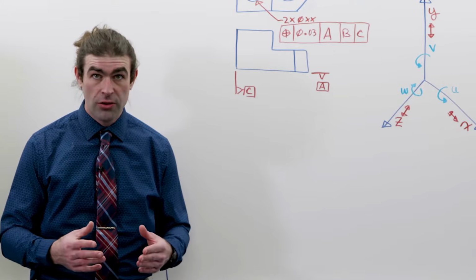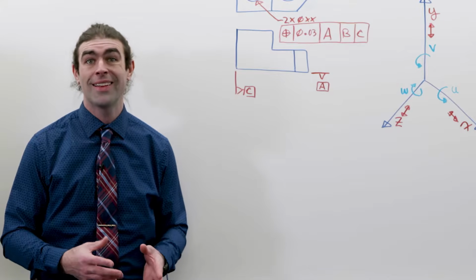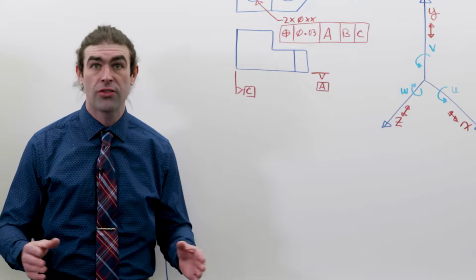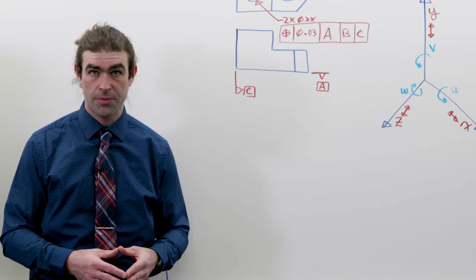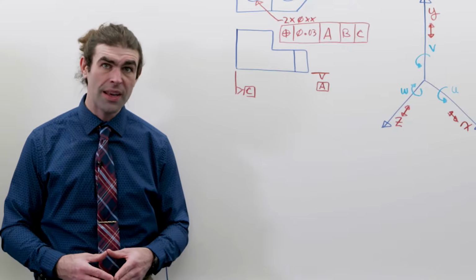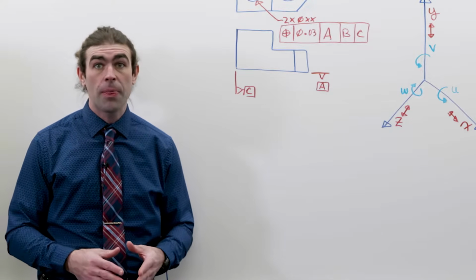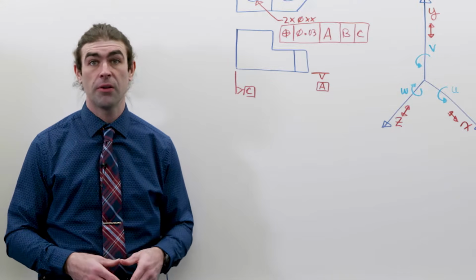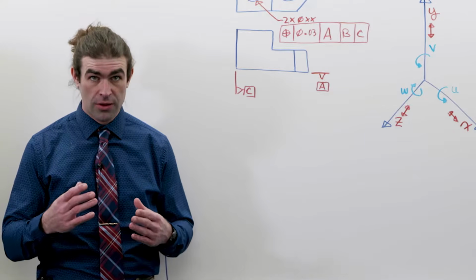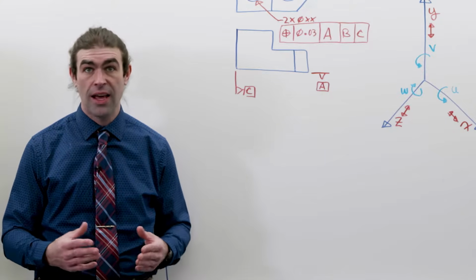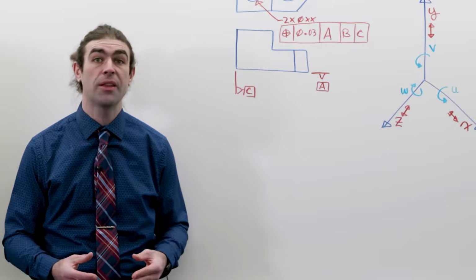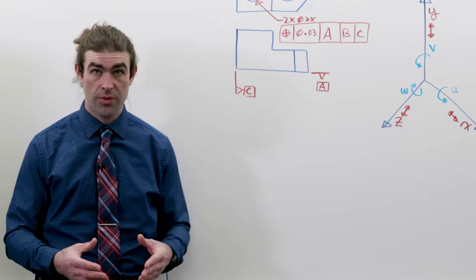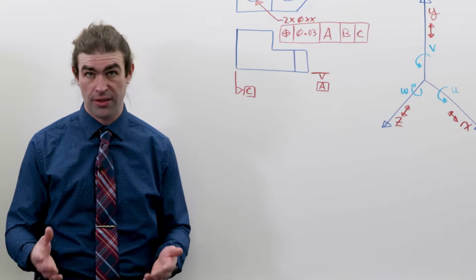So in the Cartesian coordinate system, you have x, y, and z. They're normally represented by lines going in totally opposite directions. They're 180 degrees from each other. They're 90 degrees from each other. Now, in GD&T, our datum reference frame is represented by 3 mutually perpendicular planes. Theoretically, they're perfect. They're exactly 90 degrees apart. In reality, they're not, and we'll at some point talk about how we square the circle with that, theoretical and what you can actually inspect.